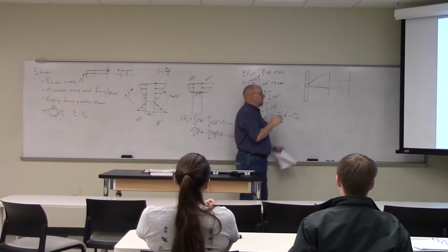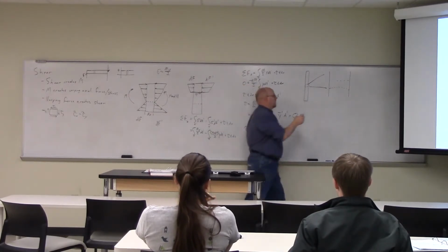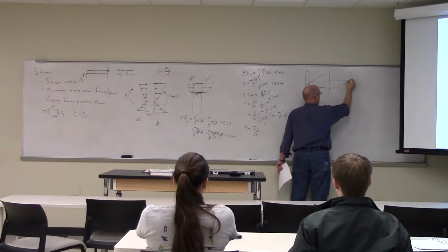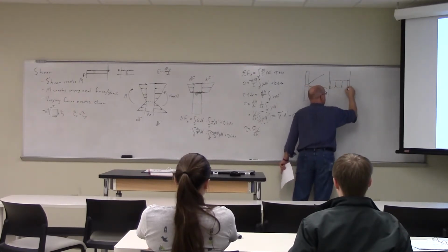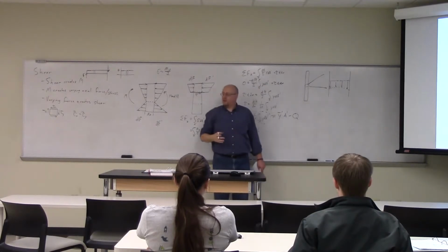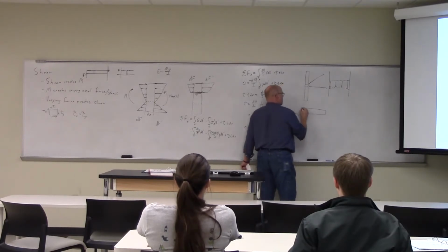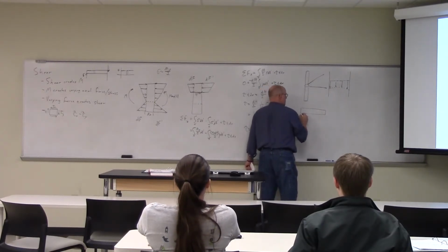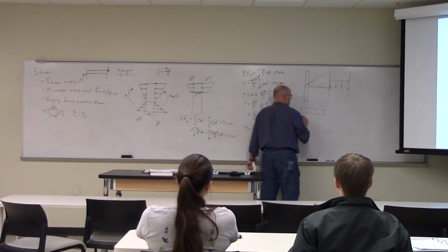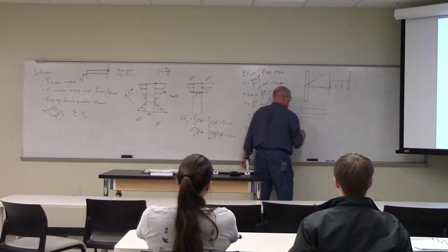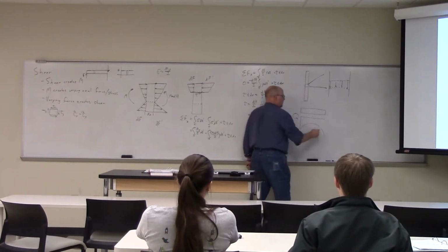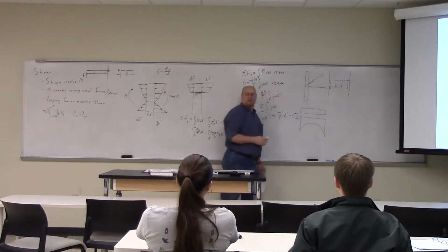Okay, you see what I'm saying? This is just a reference line. So the shear stress amplitude is slightly more at the sides than it is at the center. Okay, but if I take a beam that's just the opposite dimension, and then plot shear stress across there, I could get a really big distribution of shear stress.